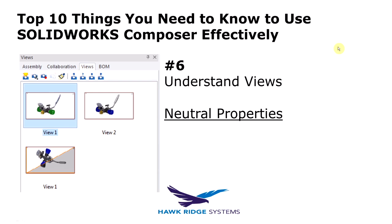If I go back to SOLIDWORKS, I can change a bunch of things in SOLIDWORKS. If I go back to Composer, nothing changes in my Composer document. I can then draw a line in the sand, save that Composer document as an archive file, and go to it 6 months, 2 years later, or whatever, and it's going to be that same file. It's not going to change with SOLIDWORKS.